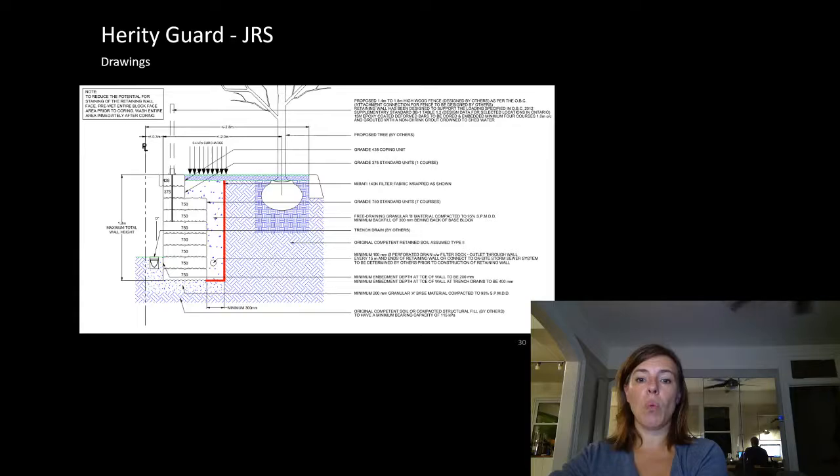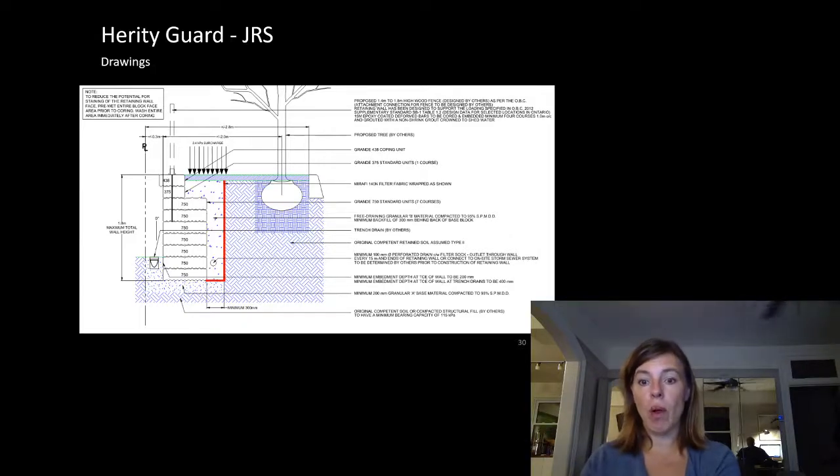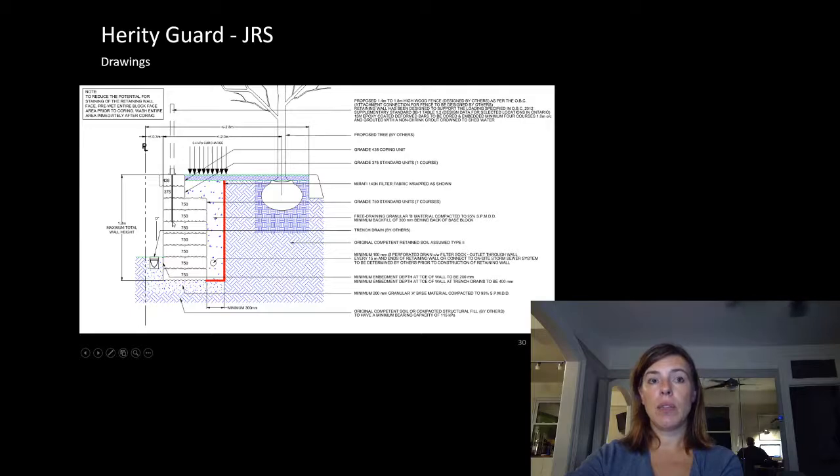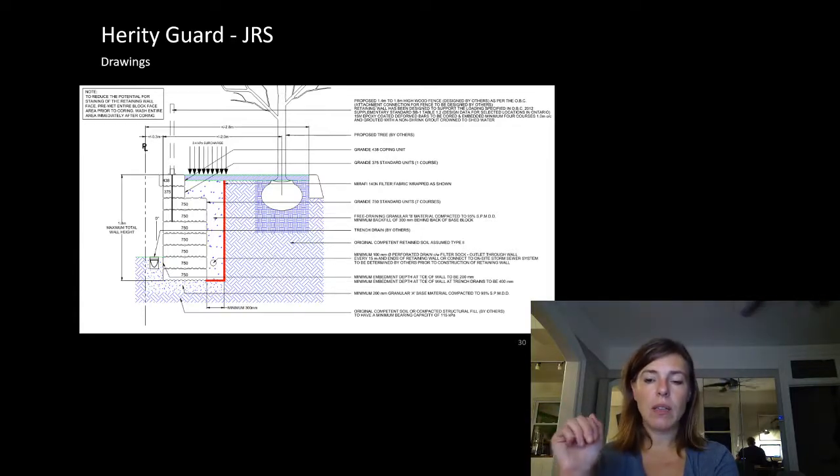Realistically, the worst case was a 1 in 50 year storm while this surcharge, so basically someone would be having a party out beside this retaining wall during a hurricane. And so we talked about the level of risk, and I said it's not my job to argue it. I just want to let you know what my calculations are showing, but they're signing and stamping it. So in the end, they accepted the armor stone people signing and stamping this, and me signing and stamping this, even though the armor stone people said they did not design this to my loads, and the owner was happy with that. Again, I did not perceive a life safety risk.